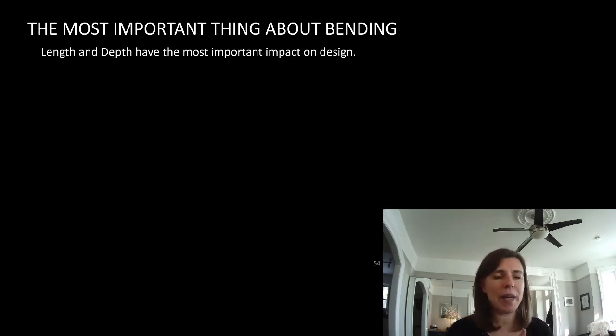We're going to have to do moment calculations, and that's mandated, and we're going to go through all of that. But here's the thing that I want you to remember forever and ever going forward. The most important thing about bending for you to remember is that length and depth have the biggest impact on the design. So let's take a look at this.